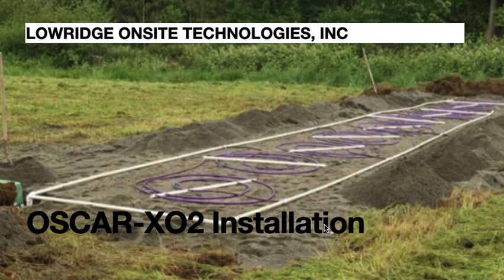There is treatment going on as water goes through this sand here, but its primary function in the Oscar XO2 is the dispersal part of it. So that's the Oscar. The XO2 refers to the pre-treatment before the wastewater goes out to the Oscar system to be removed, and that's an aerated ATU system. And so we'll get into what those components are, but it's one system, the Oscar XO2, with two components to it, the Oscar drain field and the XO2 aeration.